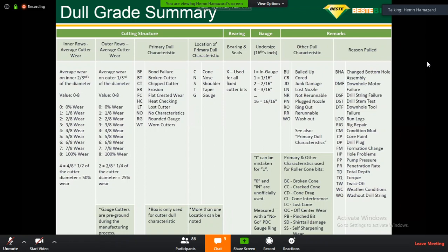The LWD, like I answered yesterday, we use it only for the interested section. In our case, it's the last section of our well, which is the 6-inch hole. The data are pretty much reliable. There's no problem in terms of reliability of the data. And we can gather a bunch of information like resistivity, sonic. We've also used neutron density, gamma ray, deep angle, image, all this information we can gather.